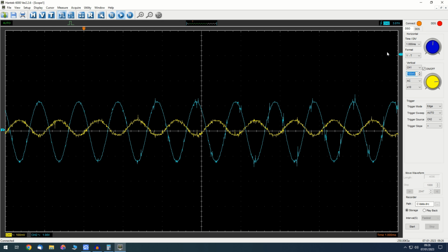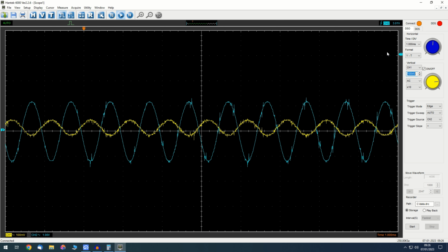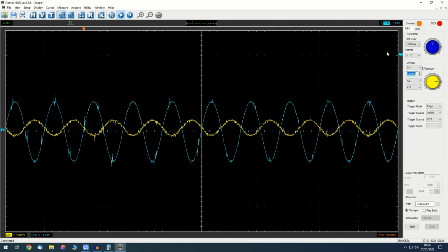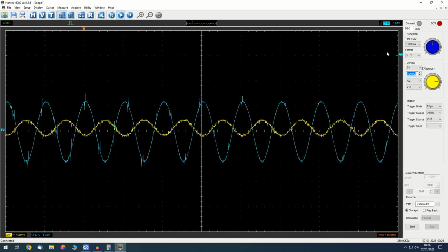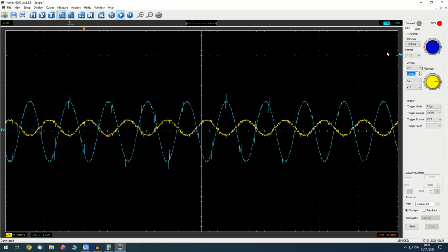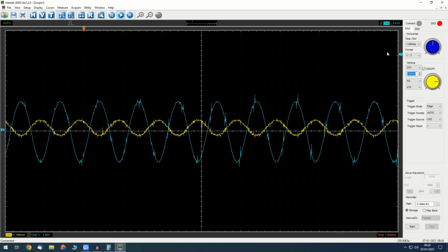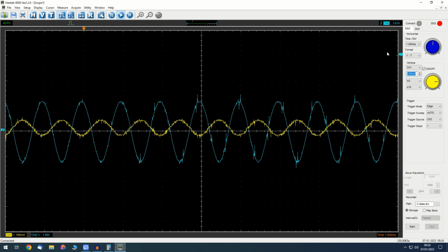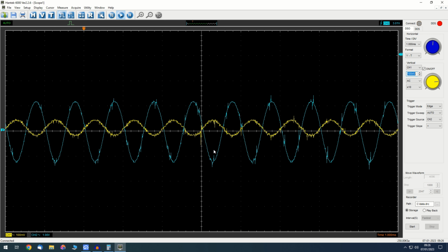So you can see how you can change the gain at AC audio, or all the frequencies, depending on what you're working with, as long as the coupling capacitor is big enough that it's not a significant impedance compared to the extra emitter resistor at the frequency you're working with.